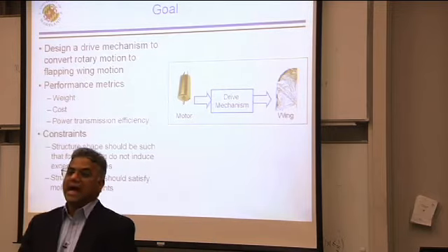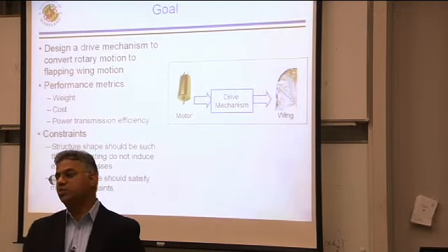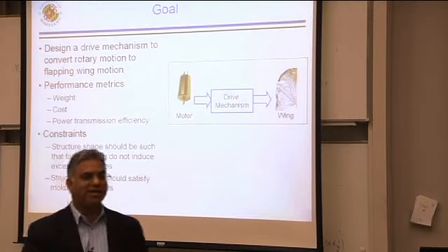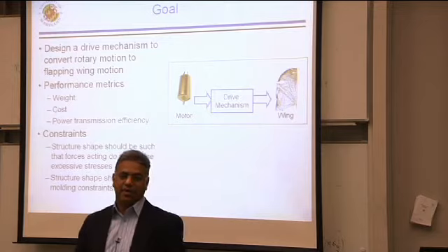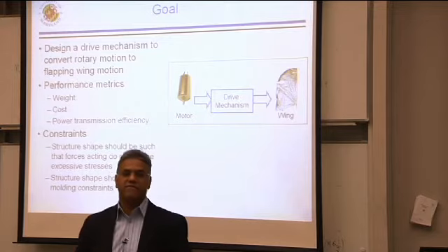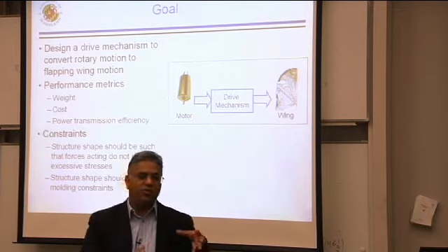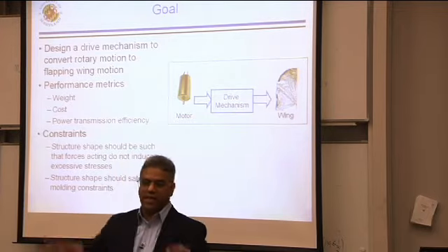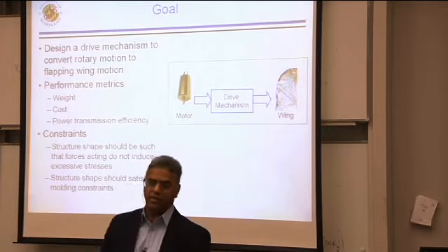Now, design of wings we have also worked quite a bit on, but we do it purely experimentally, so that doesn't fit the theme of the talk. The reason is that when you're trying to do these flapping wing flights, aerodynamic calculations are extremely difficult, and you cannot do them with reasonable accuracy. So we do our wing design basically on a test stand, by putting these wings and flapping them and doing all kinds of measurements on it.